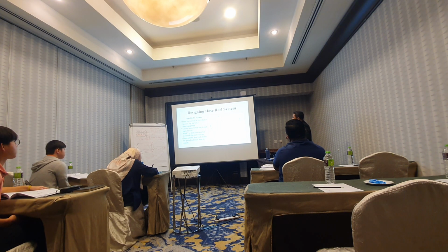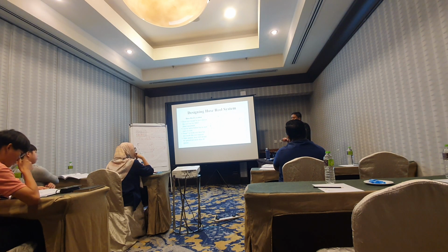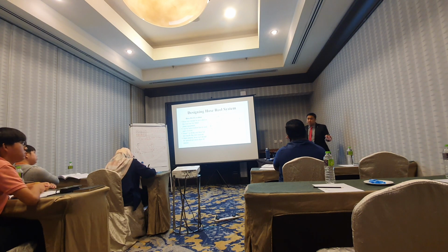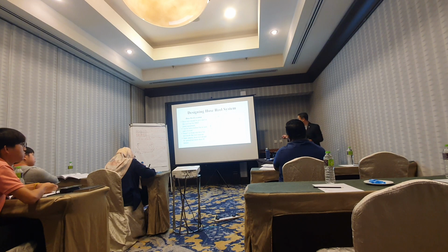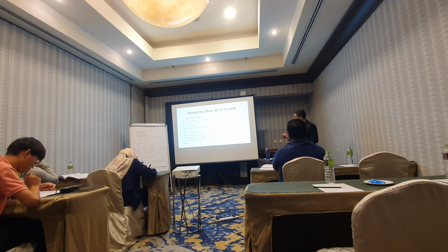Okay. To design a hose reel system, the hose reel location nowadays you need to have this arrangement lah. This is for open site, open parking ataupun gudang yang open. Maksudnya when you design an open space yang besar, this is how you arrange the hose reel lah. The hose reel must have overlap like this. So the distance between the hose reels can be given is 48 meter.